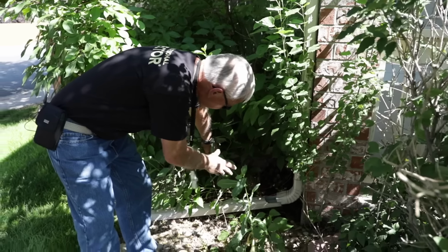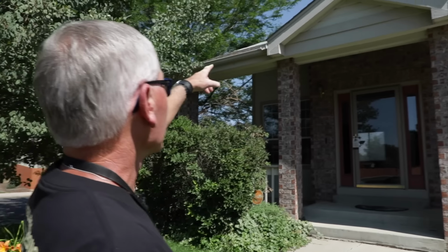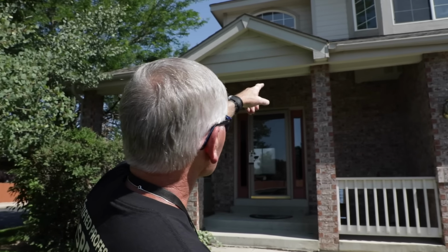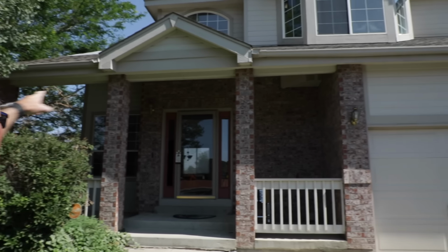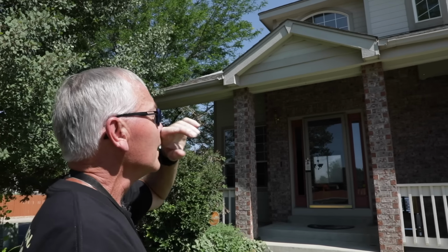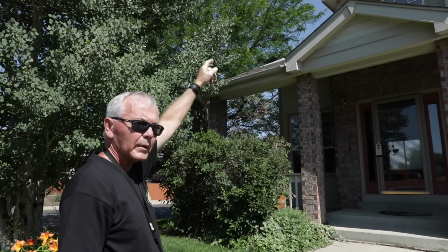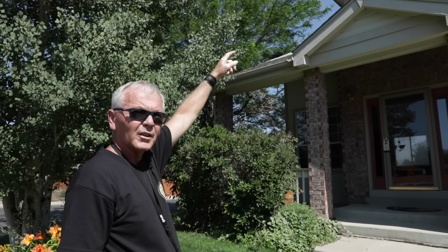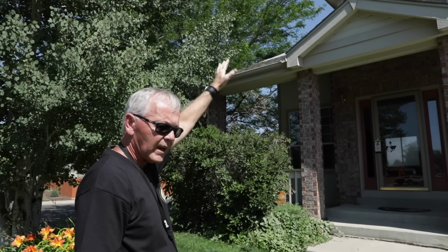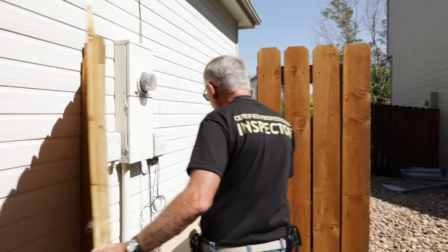Now we're going to move on to the vents, flashings, and chimney or any roof penetrations in the SOP. And from the ground here right away I can see that I don't have any drip edge flash anywhere on this roof. So I'm going to put that in my report and recommend that. All of the plumbing vents up on the roof, the top end of the roof, all look pretty good. So we're going to just leave that. I won't have any notes in my report with that. So now we're going to go check the chimney.